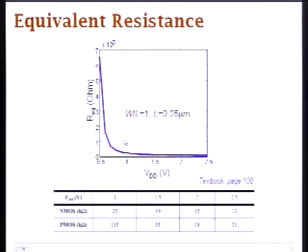And you see that as you decrease your VDS, your resistance first stays fairly constant and fairly linear in VDS, and then when you reach some point where you are going to turn off your transistor at around 0.5 volts, your resistance increases by a large amount as you traverse from saturation, going down that curve into linear mode and then finally cutoff.